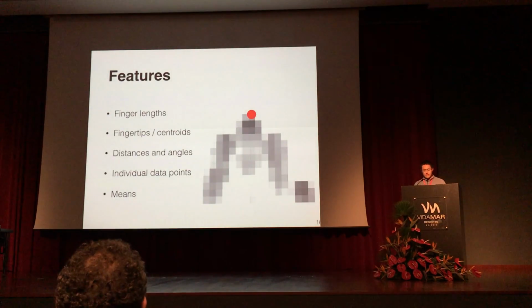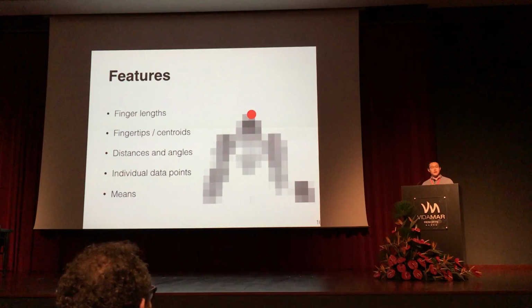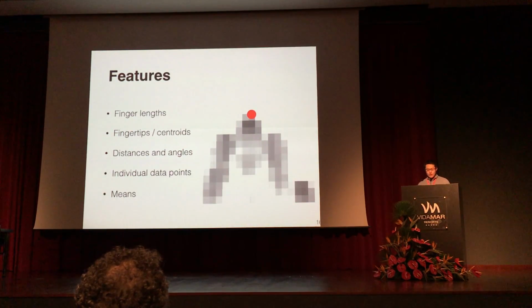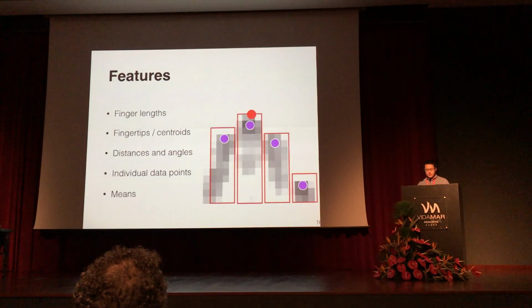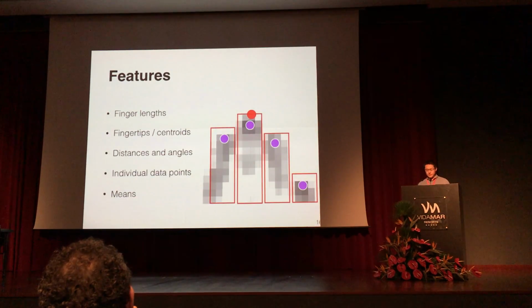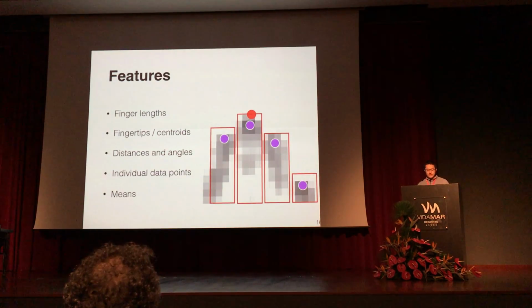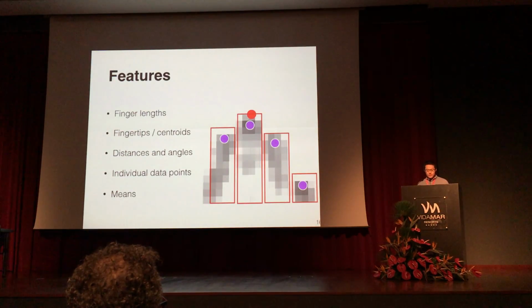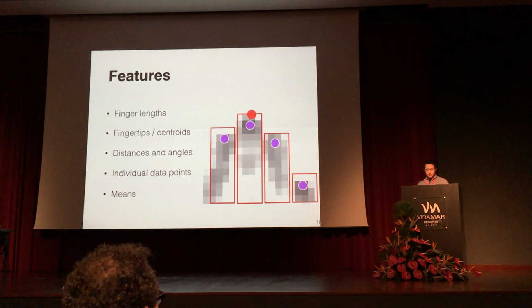We derive a series of capacitive and geometric features from the capacitive image. We extract the positions of the 4 fingertips and the attached fingers, and then calculate the statistical features of each finger. For example, the length, capacitive weight, width, geometric centroid, and also pairwise distances and angles between the points. We also included the raw value of each point, mean values, etc.